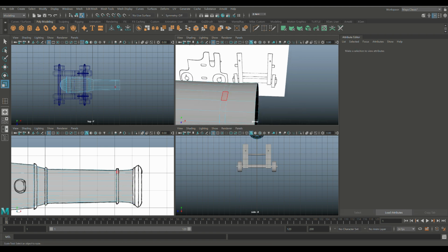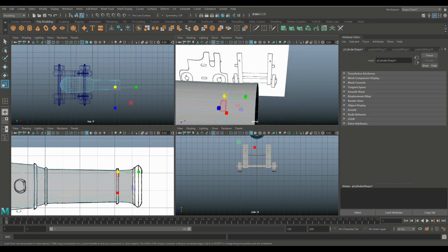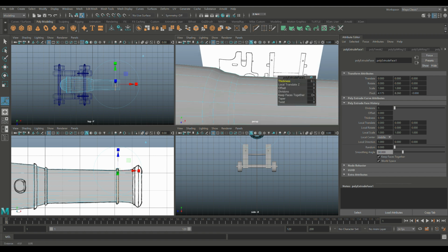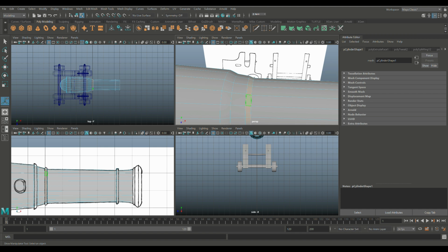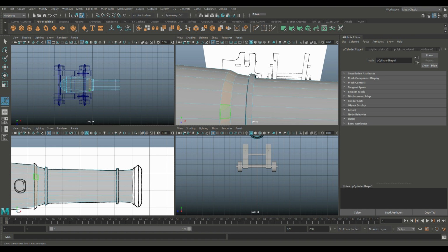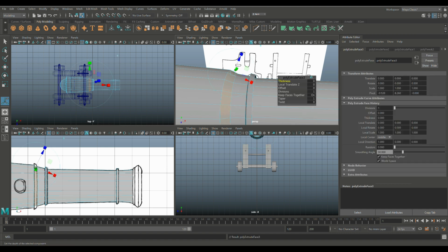and we're going to right click at a face and shift double click, and we're going to hit Control E to extrude, and let's try 0.1, which is, I would say, about okay. Then we're going to go to the next section, Control E, let's try 0.1. Let's take this guy, G to repeat last command, 0.1.